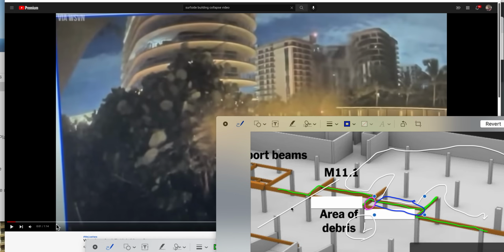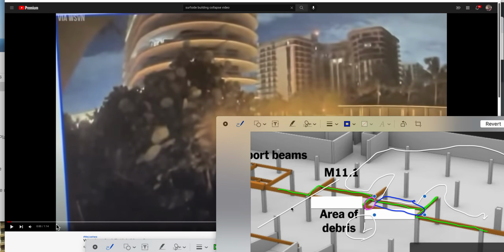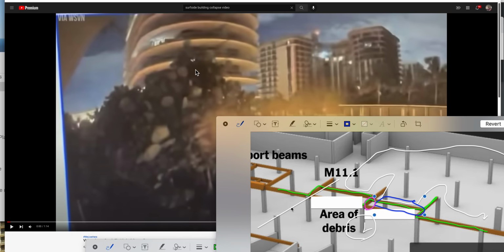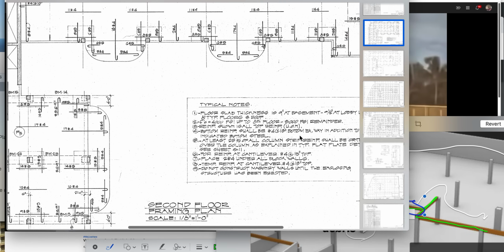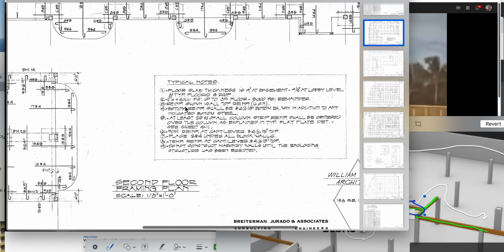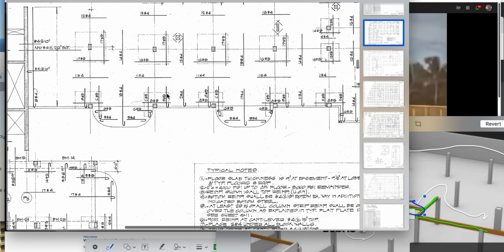And lo and behold, we get about an 8th floor failure as our buckling point. As the building was rattled, 8th floor on L, that's too much of a span. So you need to focus on L and its loading around the 8th floor, and its interaction. So 8th floor is 3,000 psi. It's 4,000 on the column, and so we are at the second floor and above.